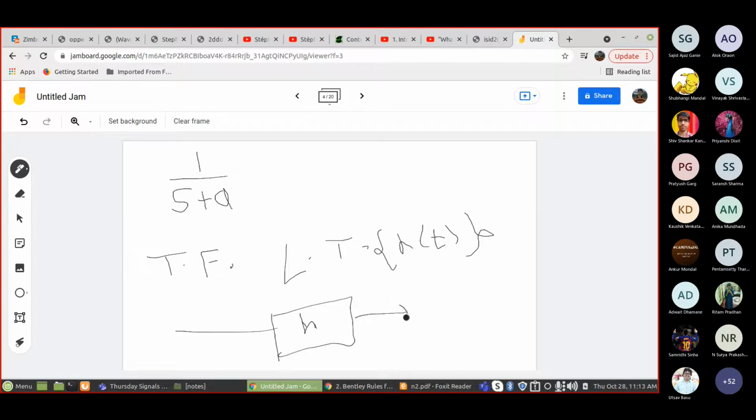So this is the impulse response, and you know that x is my input, then y is given by x convolution with h. So this is h of s. This is what we call the transfer function of this system. And now by the convolution multiplication property, we have not shown this, but we will show this, this is x of s times h of s.